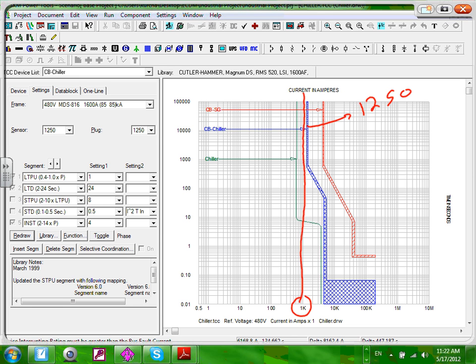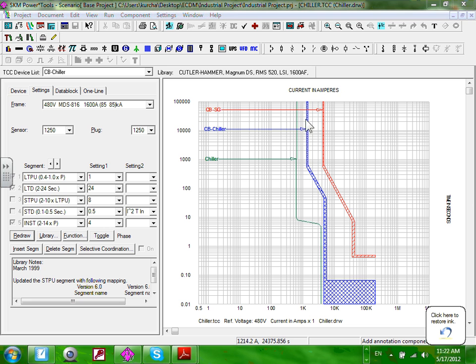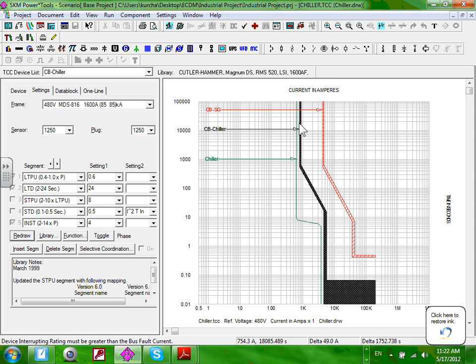I just moved it. Look at my setting right now. I changed it, but I have mine set at 0.6. Yet the current value is well over 1,000. So if you click this one and drag it all the way to 0.6, like you said, the pickup value, if you hover over it, should show at the bottom here. It says 810 amps right at the top of that black curve.